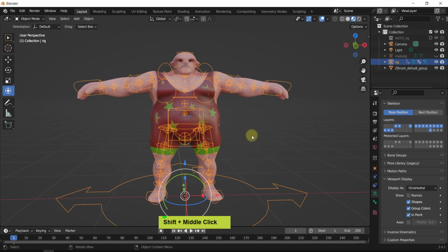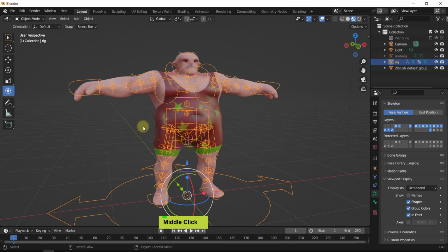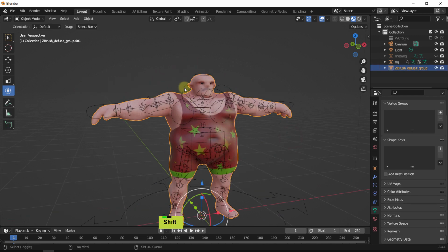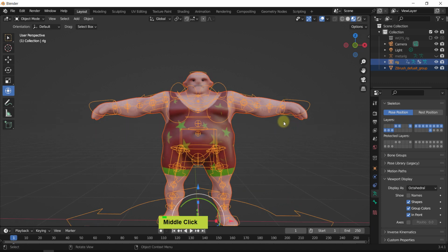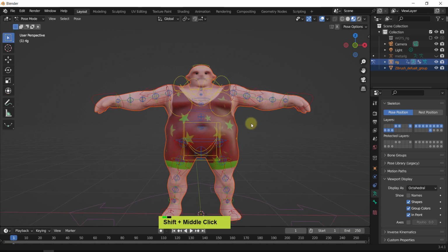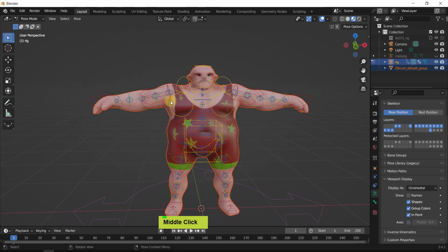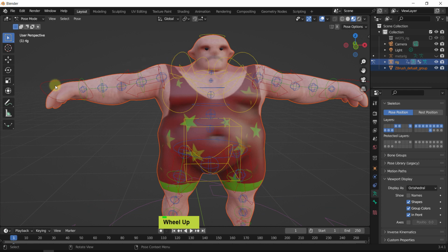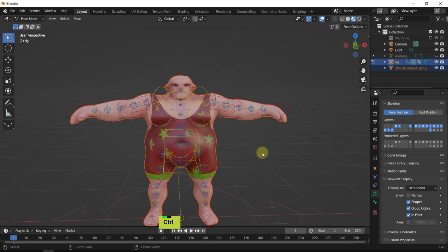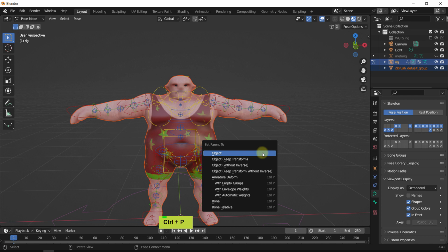You may think that it is done, but not. We have to tie the 3D mesh to the freshly created armature. To do that, select the 3D mesh, hold down the shift key and select the rig. Now we are in object mode. We can go to pose mode, where you see the colors, and you also have to see the highlights in a darker orange. So that's where we are, and then press Ctrl P.